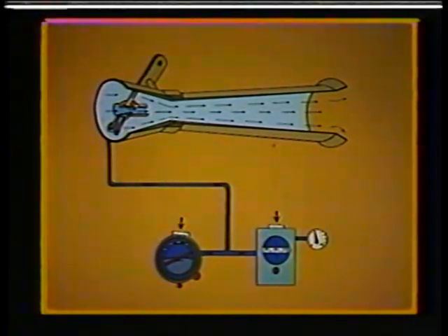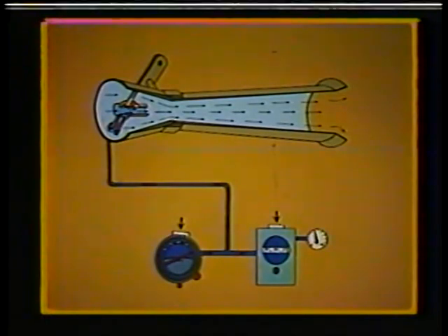Modern aircraft pneumatic systems evolved as a result of demands for a constant air source necessary to drive navigational, gyroscopic instruments, and many other aircraft systems. In the early days of aviation, this air source requirement was not nearly as important as it is today. The crude gyro instruments were simply spun by a stream of air flowing over buckets cut in a rotating wheel. In some models, airflow was accomplished by evacuating the gyro case by venturi tubes located on the outside of the aircraft.